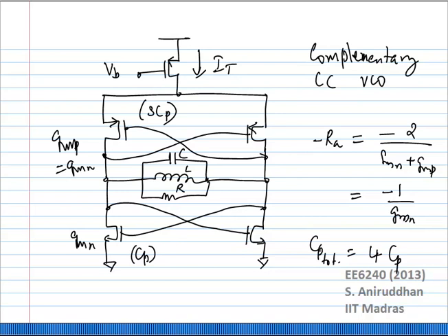Okay. Now, having seen that, we decided to look at one of you suggested this architecture where instead of using only an NMOS cross-coupled pair, we use an NMOS and a PMOS cross-coupled pair. Right? And one of you said, for example, that it's actually reuse of current, right? And I showed you an example of why it really does not reuse current. What was suggested was you're reusing current to get more negative resistance from the PMOS and the NMOS.